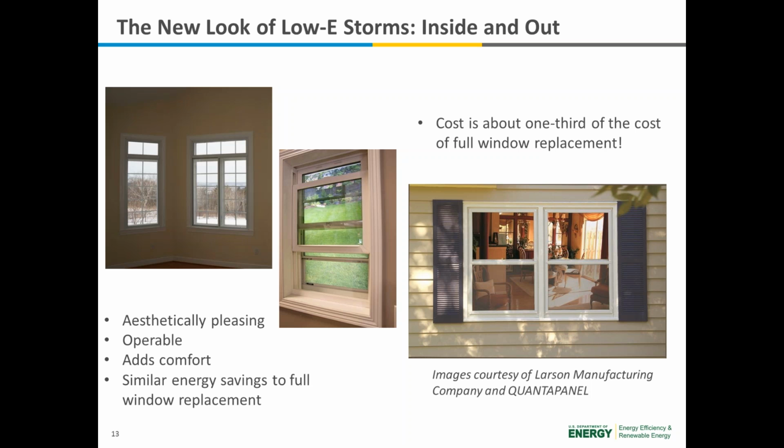But we did want to emphasize that, of course, if your existing window is deteriorated, the frame is rotted out, you have other problems, then replace it and use as high of a performance window as possible. But where it's impractical or undesirable to replace the existing window because of either cost or historical considerations, then low E storm windows are a very good option.